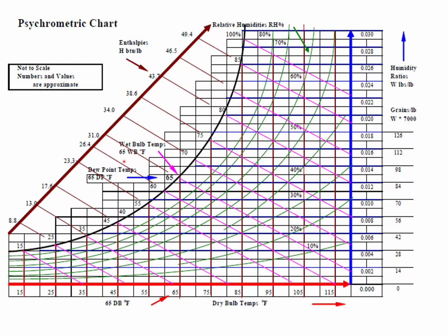Okay, then there are some curved lines. This determines the wet bulb temperature. These are the wet bulb temperatures. You can see another graph here, which means specific enthalpy. Okay, the heat required or released during the psychrometric processes. Now we'll see this step by step.